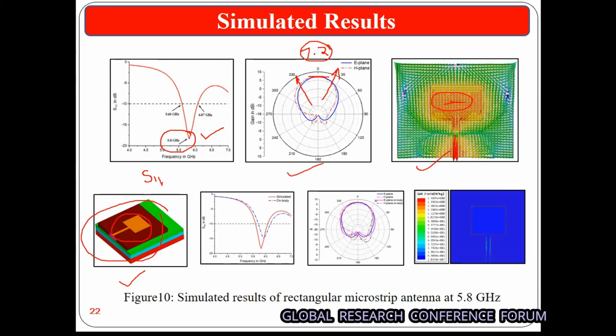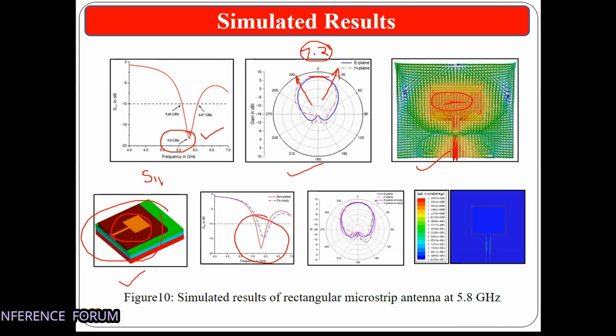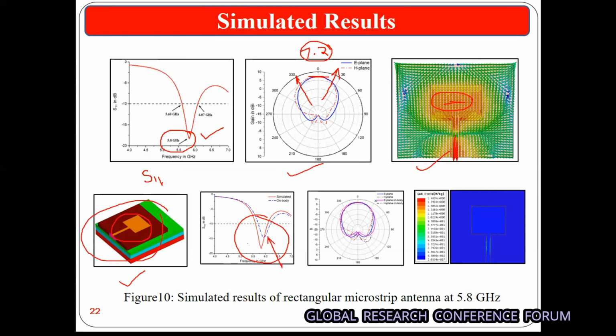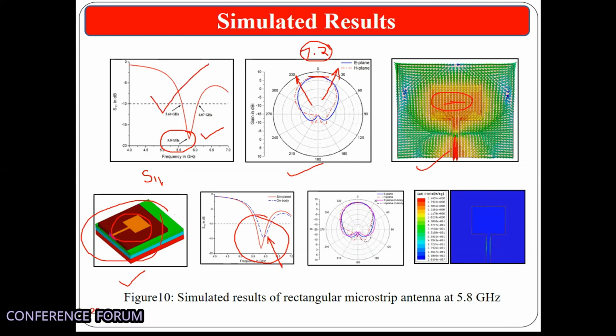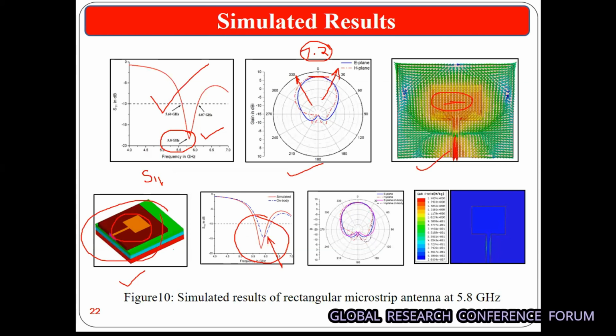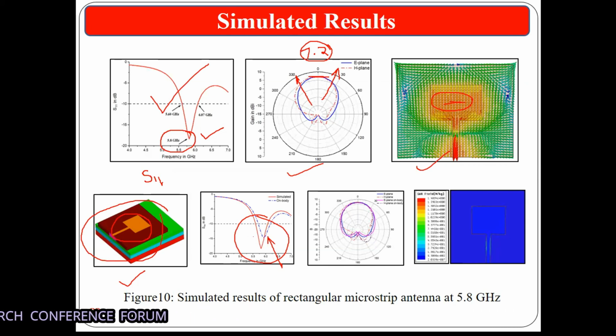So under this also, I have checked the value of S11. It is also resonating very well. It is shown with the blue color. It is slightly shifted in comparison with the original one. But whenever we compare this with on-body performance, it is obvious because our body is completely lossy and some sort of EM wave absorption is possible. That's why my pattern is shifted.